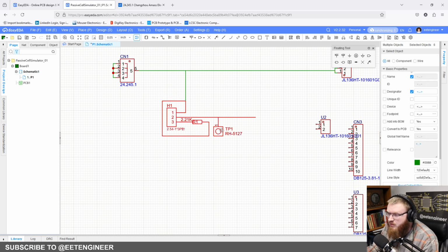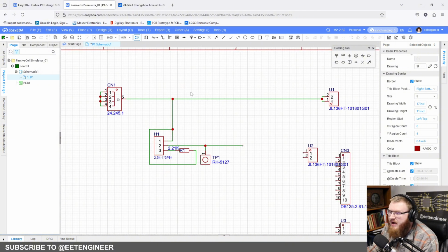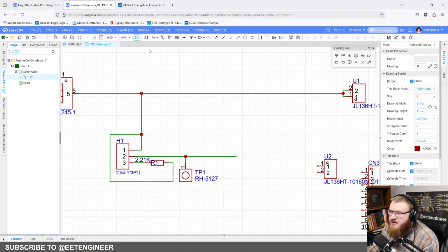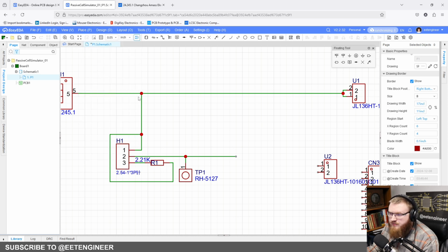This is the way we're going to stack this up, and then we're going to copy and paste this. However, I want these to be 2 different nets. I want these to be 2 different things. I want this net to be cell 16, and I want this net to be battery plus. So what I can do here is place a short. So I want to place a short flag, which is sort of like a net tie, except it does not actually have a physical footprint associated with it. It is just a virtual net tie is all it is.